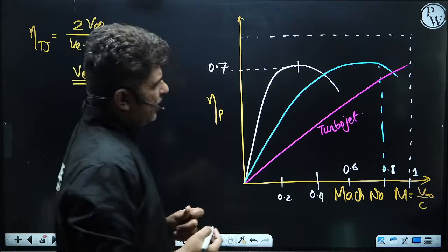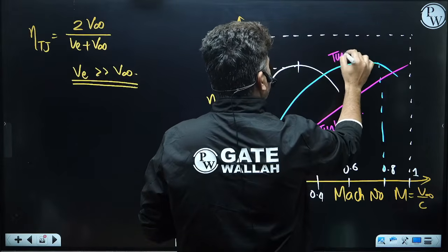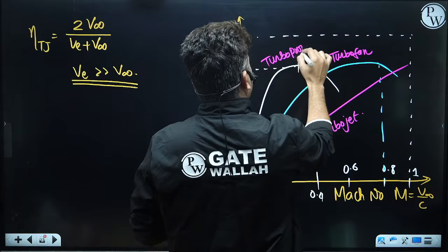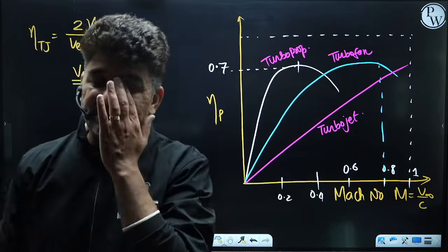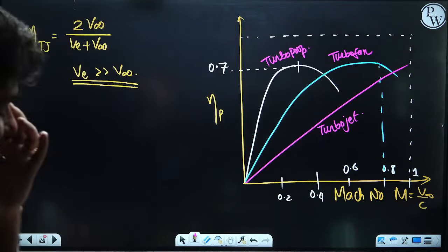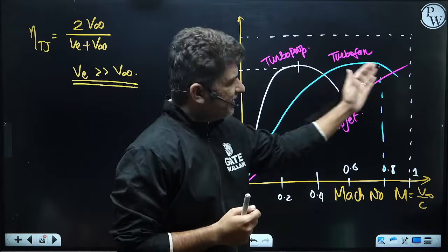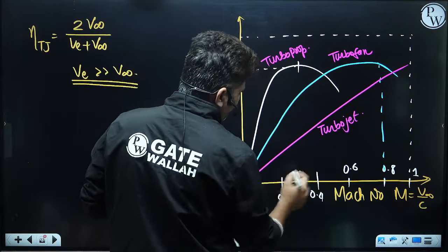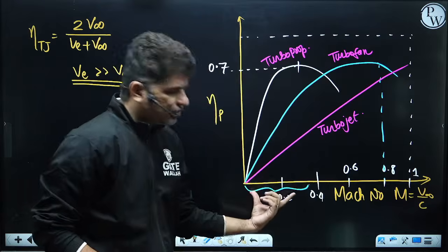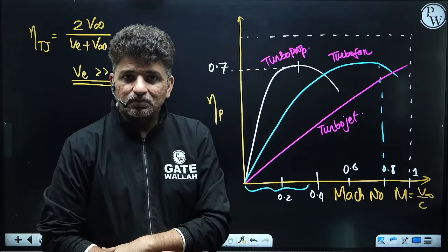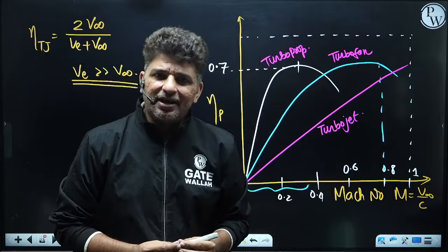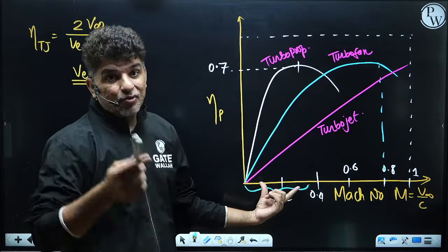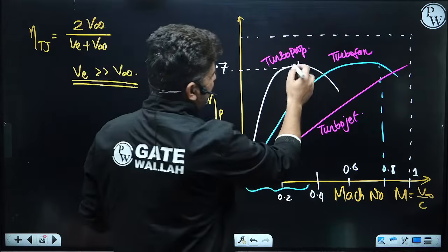Okay. So turbojet, then you have turbofan and turboprop. So you see why most of the airlines have turbofan engines. You see that there are different applications based on the propulsive efficiency. So if you are operating in a range where the aircraft speed is much smaller, so very small aircraft carrying 10 passengers or 5 passengers, 7 passengers, very small private jets. Most of the private jets, you will see they will be having a turboprop.